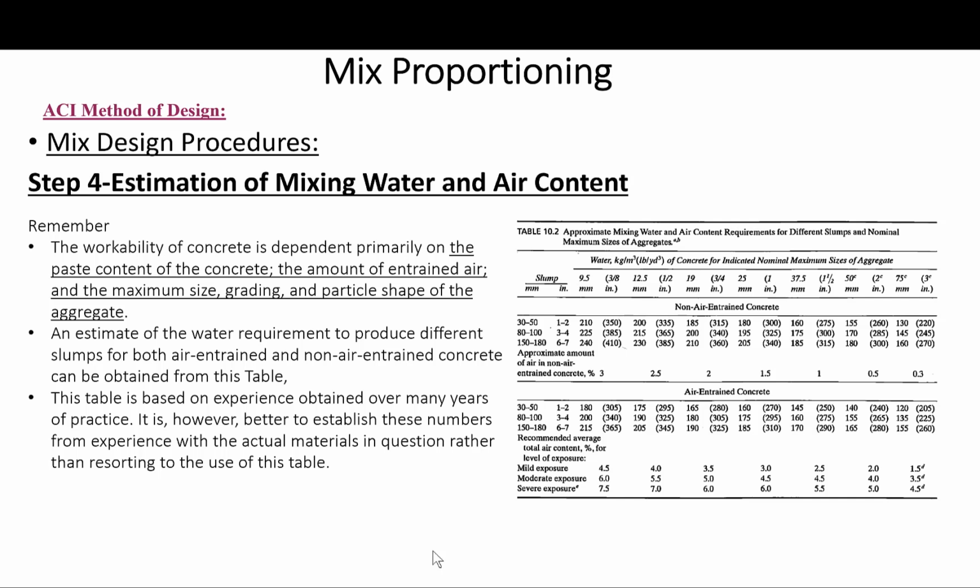Also, since there is frequent pressure from the job site, as I said before, for concrete with more slump, which is unfortunately often obtained by adding water rather than adding paste, leading to a high water cement ratio and lower strength, it is suggested that the trial batches of the mix used to develop the strength relationship be made to represent the most unfavorable combination of the air content and water content.